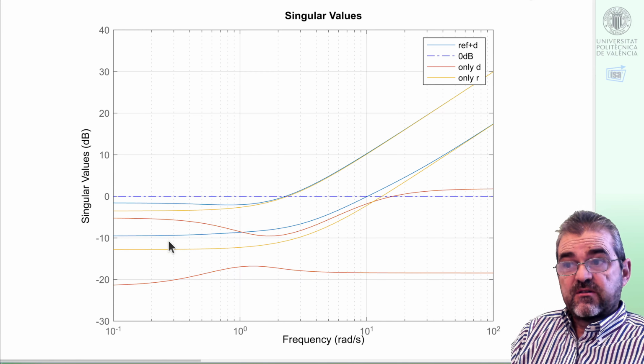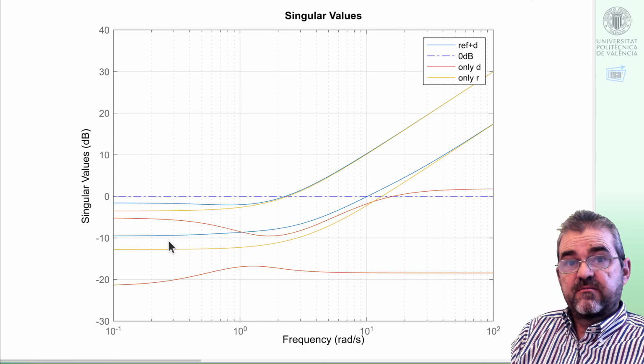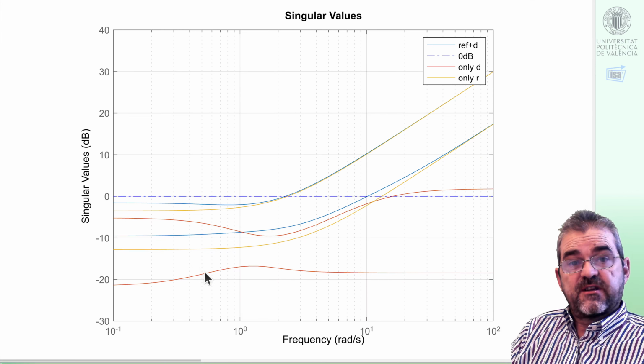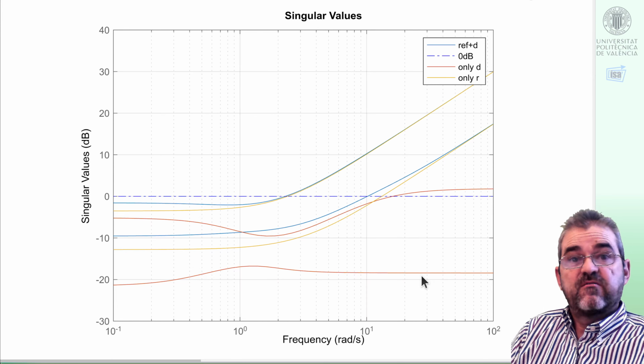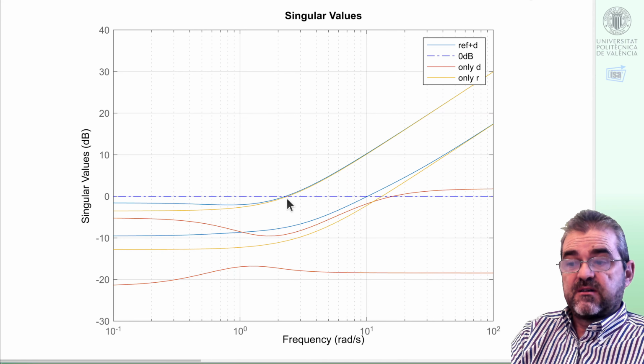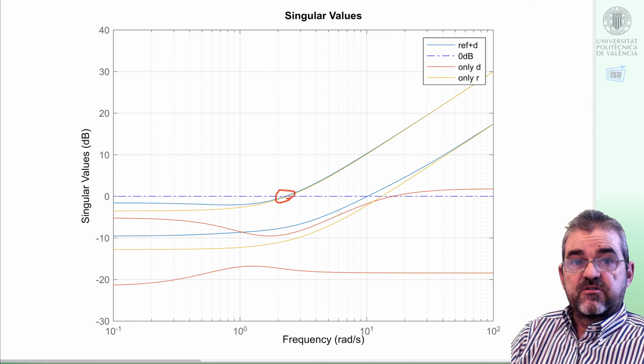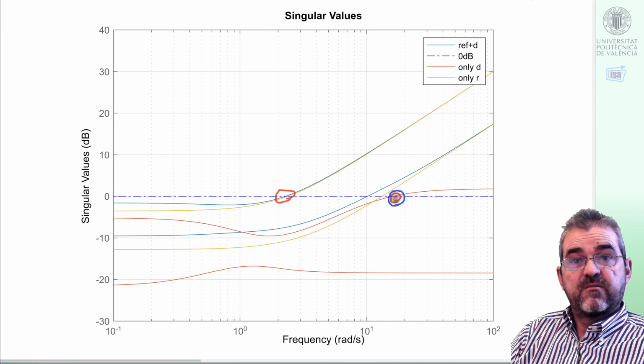Recall that the units of these transfer functions we are comparing, the outputs of them are manipulated variables U, so an easier problem is the one with lowest required manipulated variable increment. So well, yellow is easier than blue, and of course red only disturbance rejection is easier than combined disturbance rejection plus set point tracking, of course. So this is the final comparative analysis, and as we can see basically in here, the difference between set point tracking and set point plus disturbance is negligible. So it seems that the difficult thing limiting my closed loop control bandwidth is that I require too high a set point. Indeed, if I require just disturbance rejection, my bandwidth will be much higher.